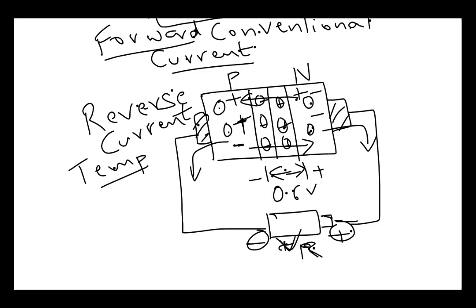If it is less than the breakdown voltage limit, the reverse current is almost constant. This implies that as the reverse voltage is increased, but if it is less than the breakdown voltage, then the current does not increase much. Thus, we can call the diode saturated, and hence this current is called saturation current.